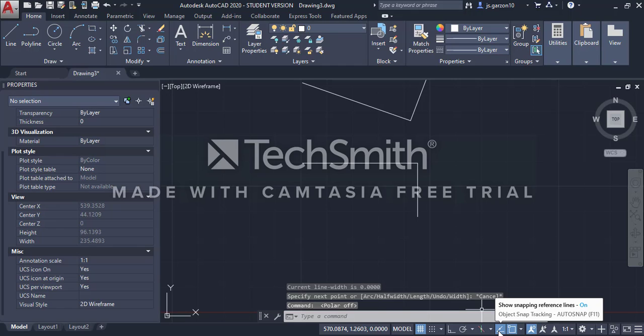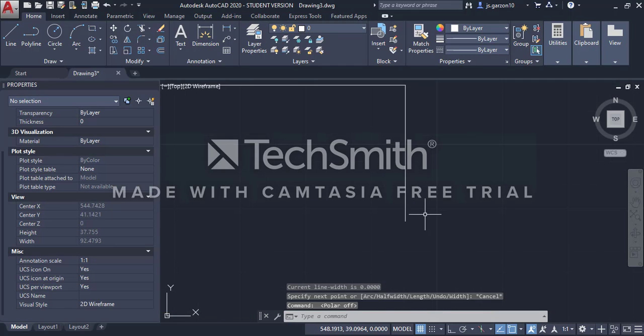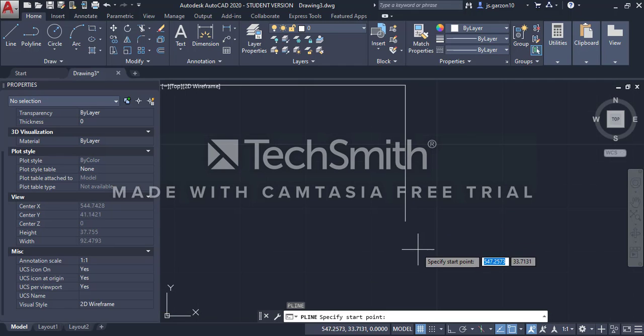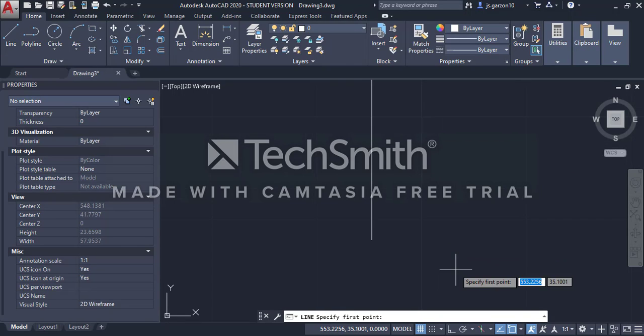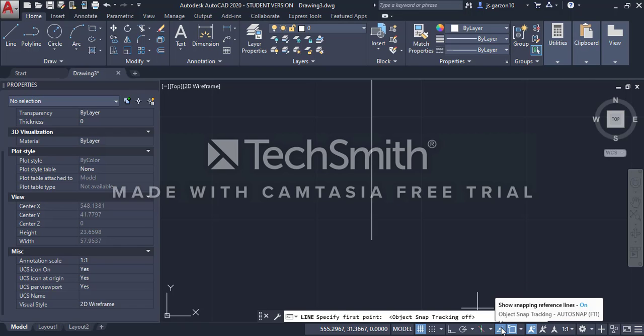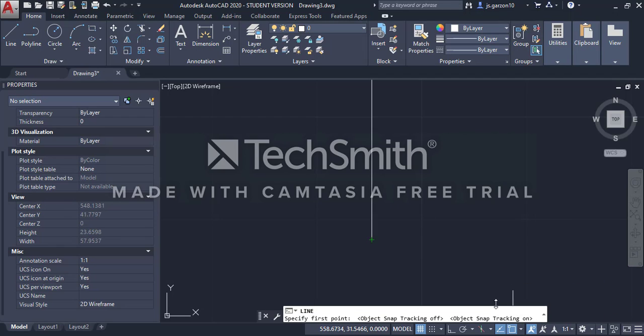This is the extension tool. This extension tool enables you to extend the lines from different points. So if you want to draw a line and you have turned off this option, you will see that there's no extension point. However, if you turn it on, you can see there's an extension point here.